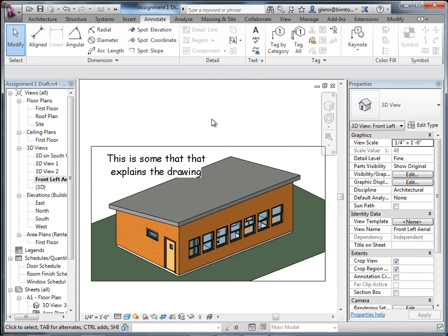And the nice thing is, if I tag my text in those types, if I later decide I want to change the color, or the font, or the size of a specific category, it will change all the instances, as opposed to having to go through and change them individually. So start thinking about your text not only in terms of literally the size, but what its function is. And give the types that way, because that will give you a lot more power later on to change it. So general rule about most of good modeling, always think about the function as opposed to the literal. Because if you code it by the function, then you can change.